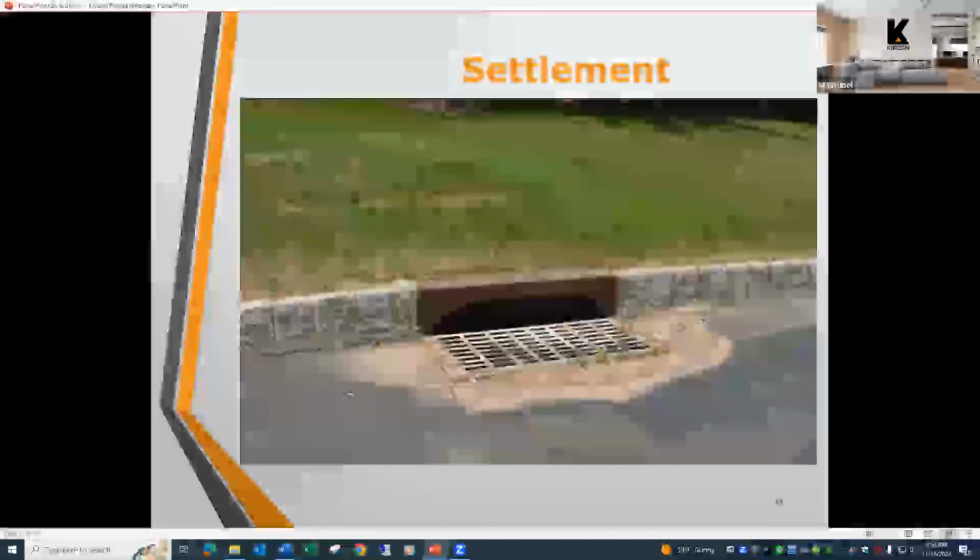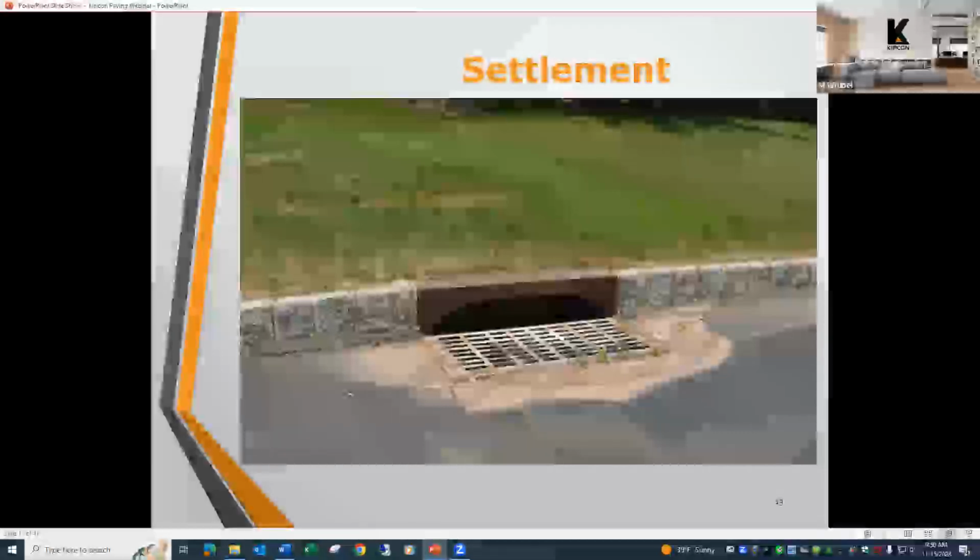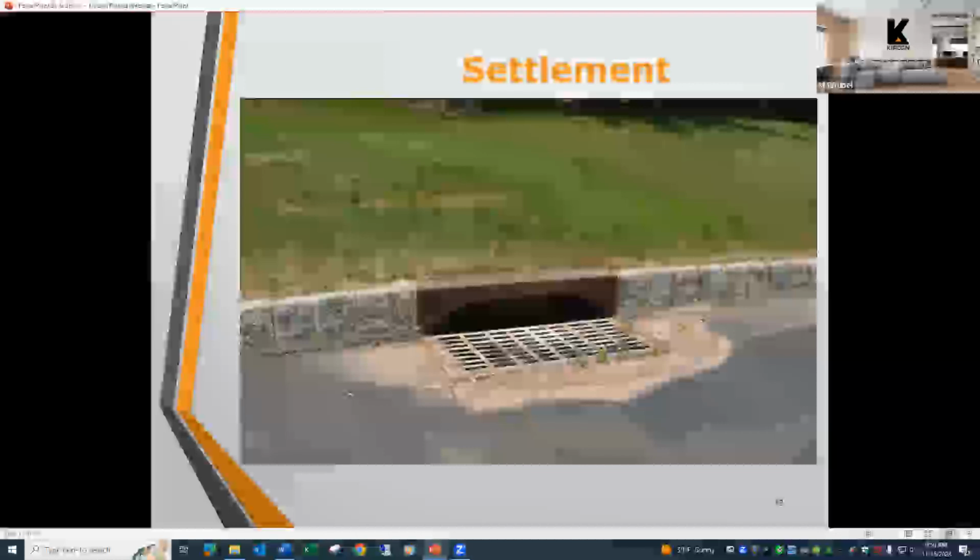Once those mortar joints are gone and the soil starts to get in, you get a subtraction of soil underneath the pavement, and you might see some settlement like this. So this is something you'd want to address. This is something we identify when we are evaluating pavement, and we might call an area like this out for some sort of repair as part of the specifications.